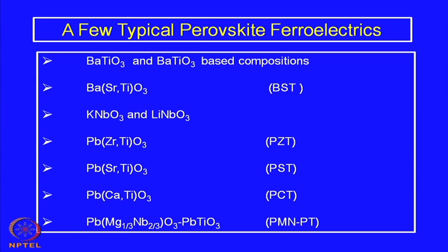Sometimes they go into solid solution with barium titanate, either substituting the barium site or the titanium site, or sometimes they remain as a second phase material. So, we have a huge family of dielectrics based on barium titanate and barium titanate based compositions. I am not going into the details of that, but there are many industrial standards available depending on what kind of dielectric somebody needs, what kind of specifications are required for a specific device, and so on.